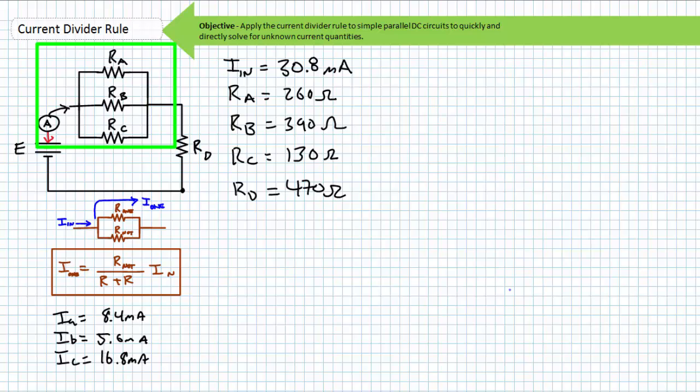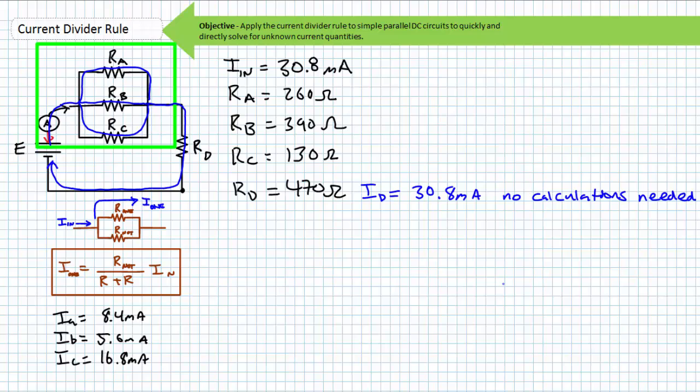Returning to the configuration of our original circuit, everything inside the confines of this box has been solved for. Step outside the box if you dare. My only advice is that you do so thinking of how current travels through this circuit. Are there places where current splits, recombines, or has no choice but to travel a single path? Can shortcuts like the VDR or CDR be applied to other points within this circuit? Will knowledge of current through a particular element give knowledge about the voltage drop across it? Will the knowledge of the summation of voltage drops within this circuit yield knowledge about the necessary voltage rise?